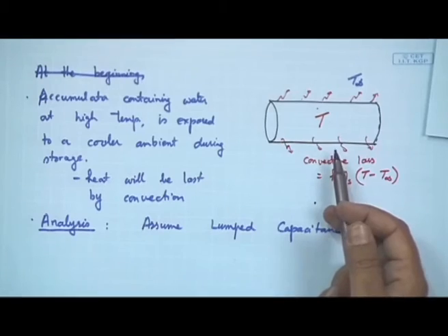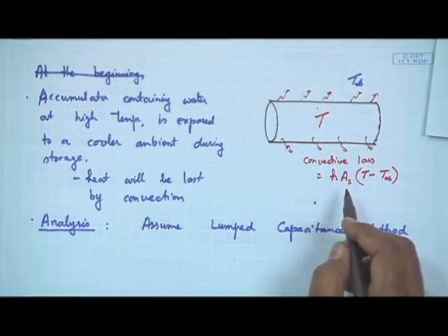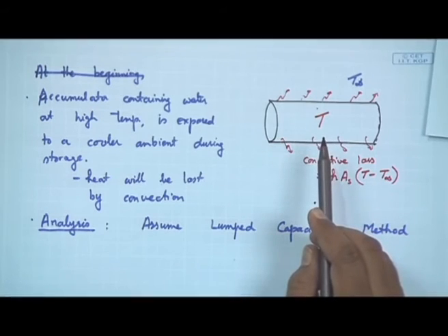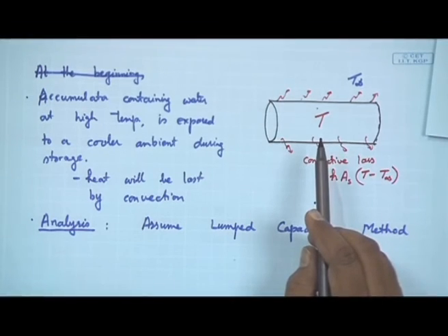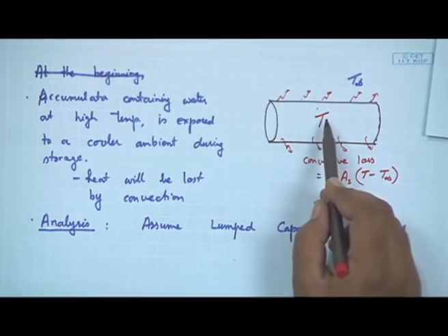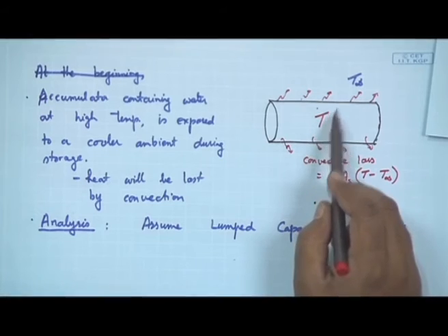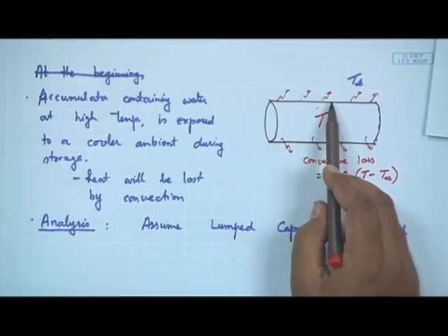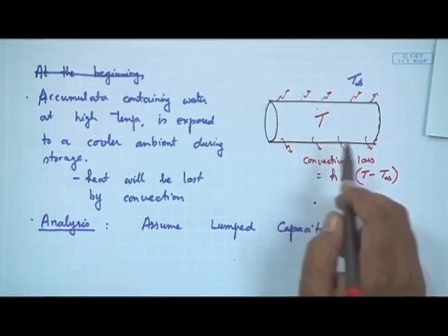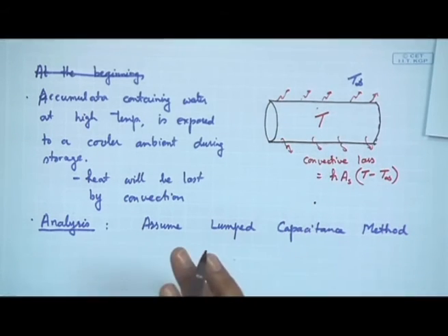We do not know. Probably the h will be low, I can say, but this is water in a cylindrical vessel, which is not known to be a very efficient thermal conductor. But still, why do I use it? It would mean that there will be some variation in temperature, and at the surface at most it will be lower. So, if I use lumped capacitance and use the maximum temperature, then I am actually overestimating the losses, and therefore, it is a conservative assumption.